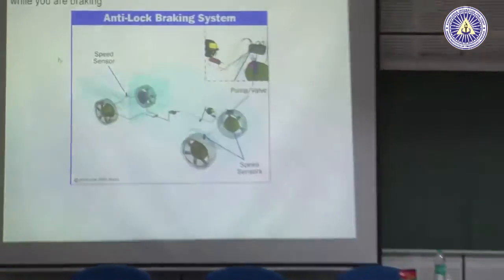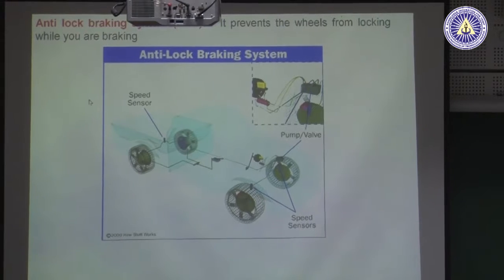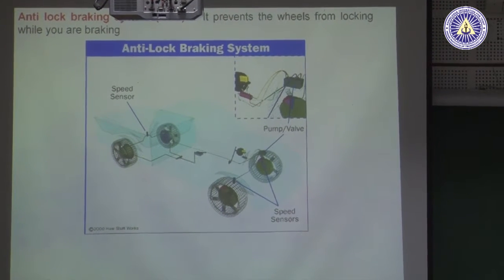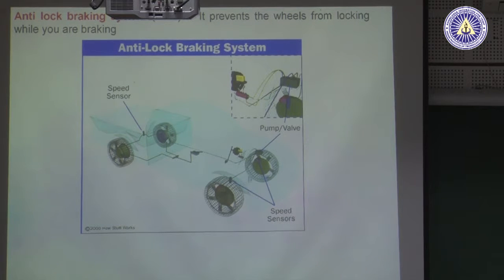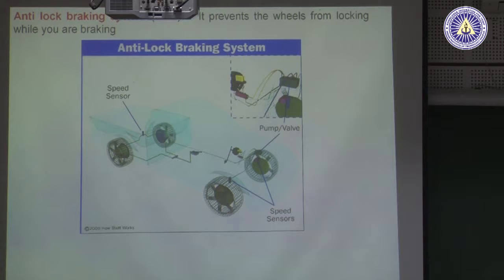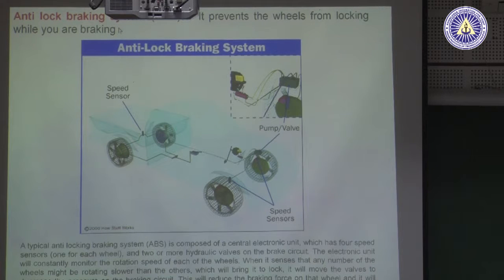There are numerous examples. For example, take a car's anti-lock braking system, right? Braking is a mechanical thing. You're applying pressure onto a wheel to stop rotation, right? But when you come to an anti-lock braking system, on each one of those wheels there are sensors mounted, and you get an electrical signal, and you find out which wheel is moving faster or slower, and thereby you adjust the pressures, and thereby you have an intelligent braking system, an anti-lock braking system, with the help of an electrical subsystem here.